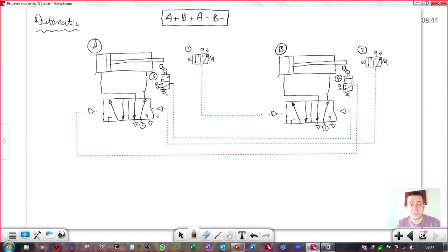And in the explanation of operation, I'm looking for a parts list first, obviously, and then I'm looking for an explanation of operation where you use cylinder A, valve 2, valve 3, that kind of terminology, but I also expect to see you putting things in order, or definitely identifying the sequence, and using terms like when cylinder A outstrokes, it actuates valve 1, pilots valve 3, outstrokes cylinder B. That's the type of language that I'm looking for in your explanation of operation.